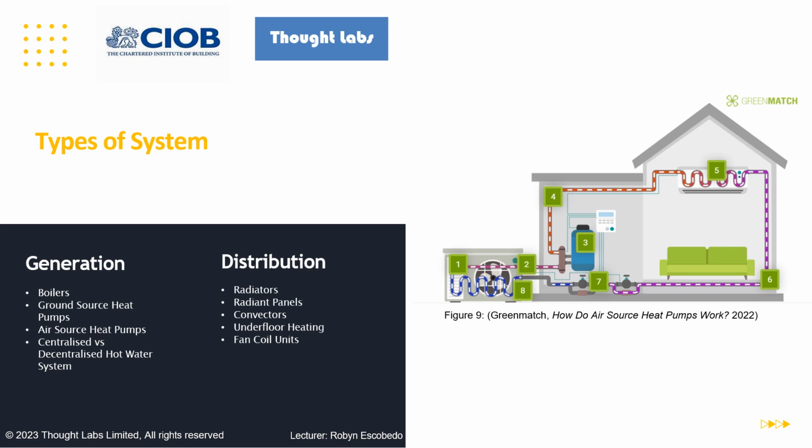If the building does not have that capacity, then you might have to apply to the DNO to increase the supply, which could have a significant cost. Also, the DNO could reject this if there's not the capacity within the area. You also need to ensure that your distribution boards have the necessary ways that would supply these air source heat pumps, and if not, you might have to change your distribution board to different boards that have additional ways.